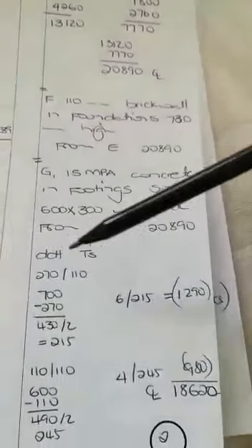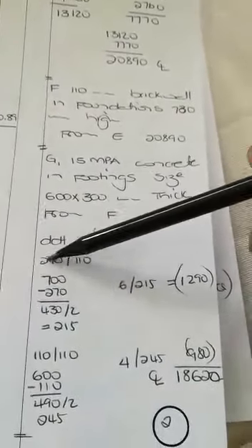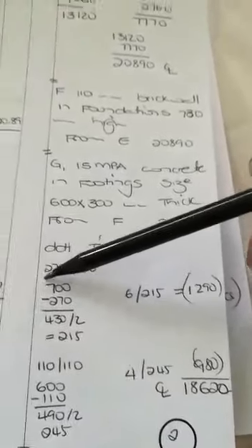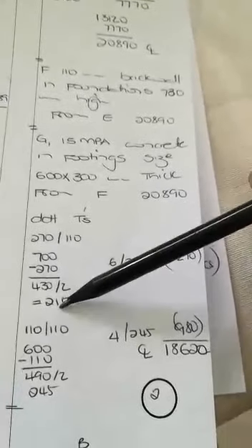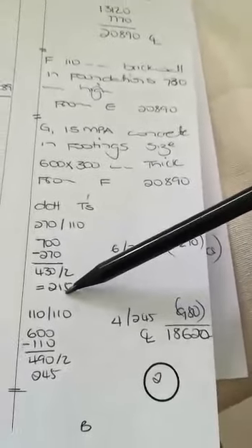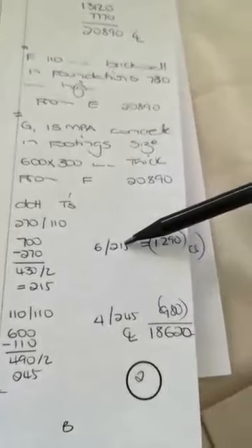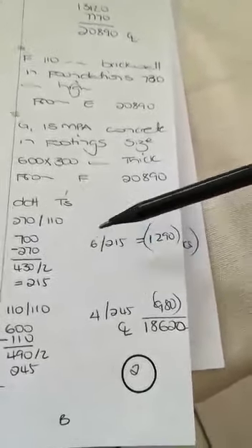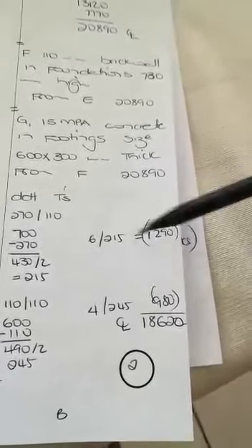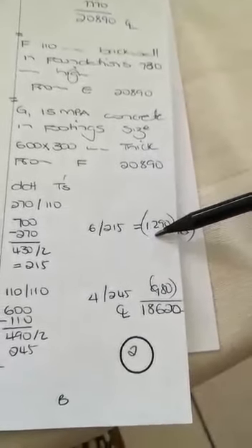So again, when we are deducting our T's, we are going to take the dimensions for our 270 brick wall. So we say 700 minus 270, we get 430, which we divide by 2, and we get that the projection is 215. So we are going to measure that 215 by 6, because that is the number of times that we have T's of a 270 meeting a 110 brick wall, which gives us 1,290.